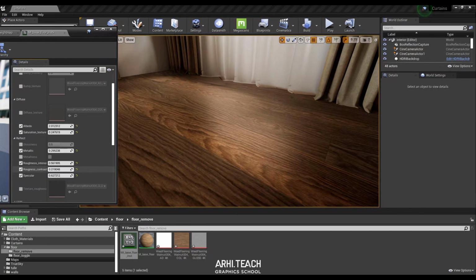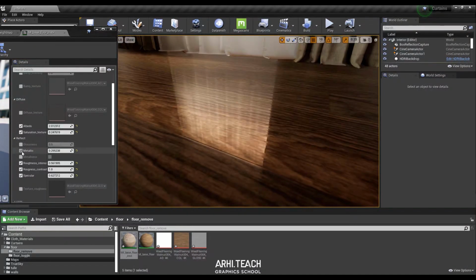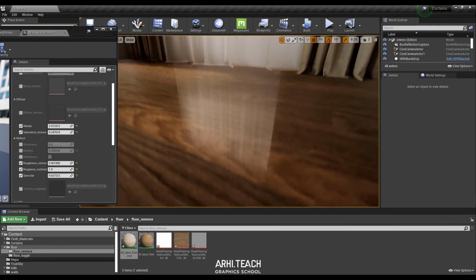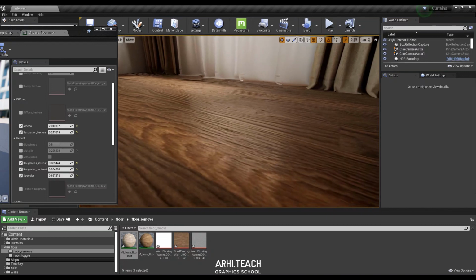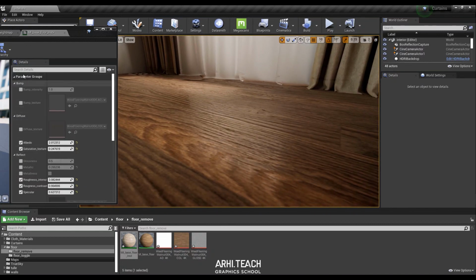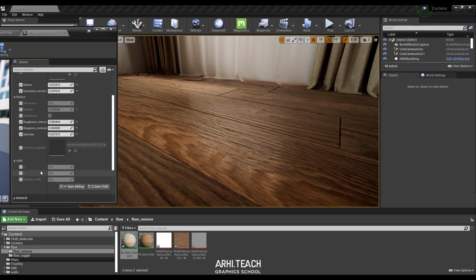Now let's take contrast. I add contrast here and our texture becomes contrasting. Now I will turn off metallic. Our texture becomes more contrasting and here with the help of intensity, we can show our streaks less or more. Let's set a bigger value for the bump until the bump shows up. You see, our seams are showing, but the texture is too huge.